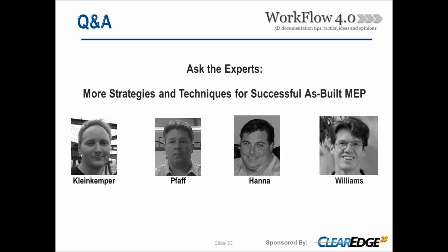I'd like to embellish on that too. If you are planning on doing cloud-to-cloud registration, make sure that you pick something that is central to the room you're working in, and that you get enough definition, at least wall or ceiling corners adjacent to where the walls meet, and then have enough data down below to get a good initial base scan for the cloud registration.